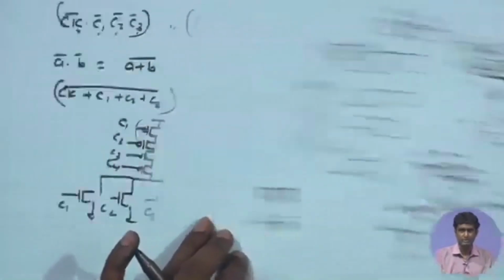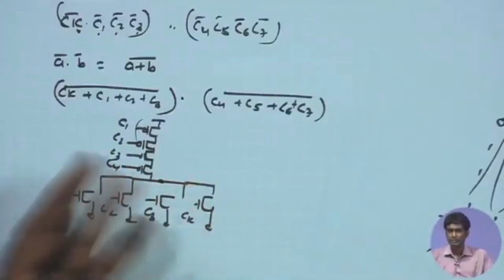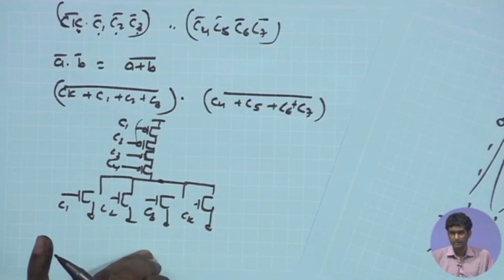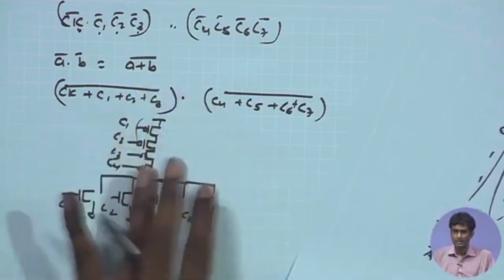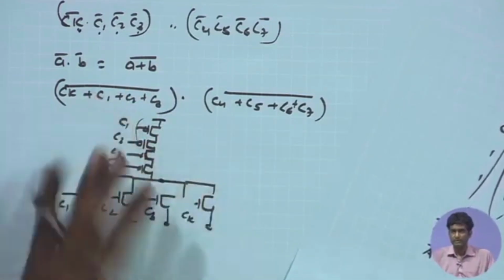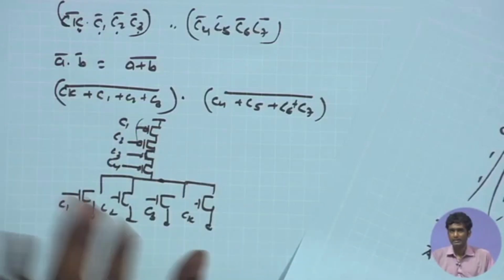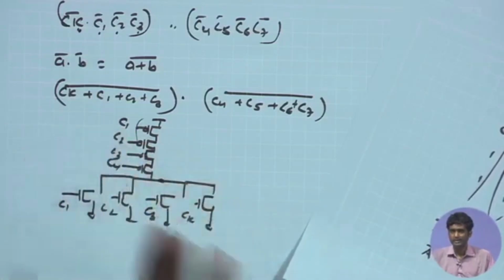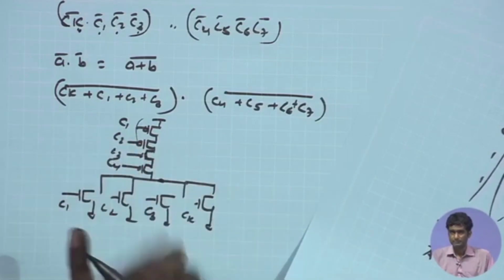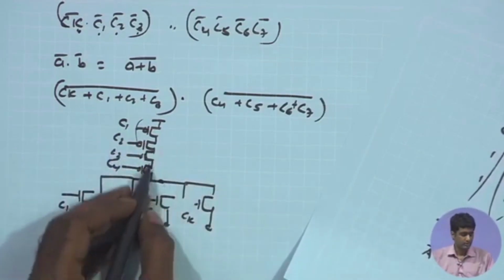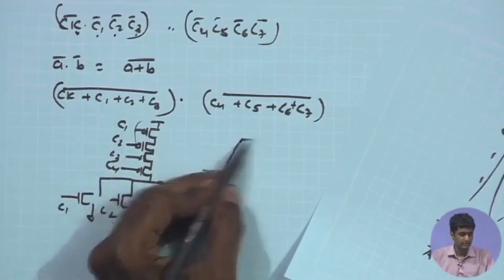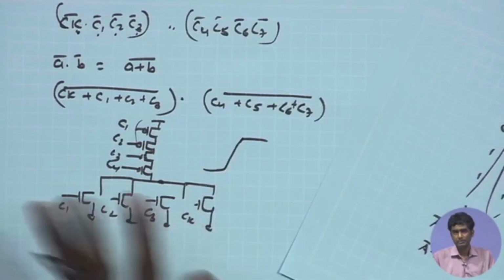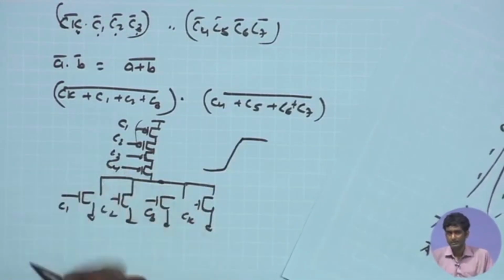So, generally for high-speed logic we may prefer NAND gate implementation, but in our case that is not an important concern, because the logic speed is not very high. As a result, we can go for NOR gate implementation also. So, we should be aware of the logic design. If you are supposed to implement any logic gate using transistors, you should know how to split it and implement it using smaller gates, so that the delay is within limit and you have the right kind of transitions. Along with the delay, another point is rise and fall time. If you stack more transistors, because of the large RC time constant, the rise time and fall time will also be degraded. So, these issues should be kept in mind while implementing transistor level logic.